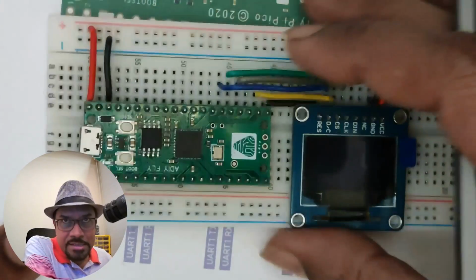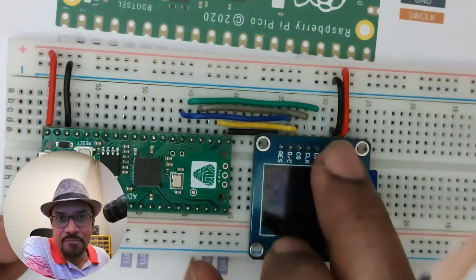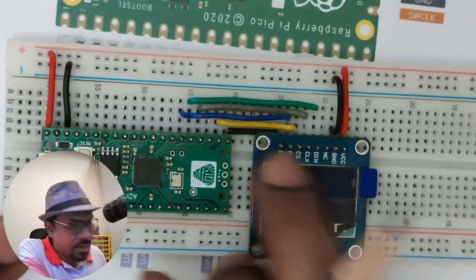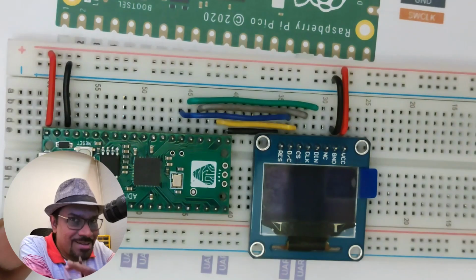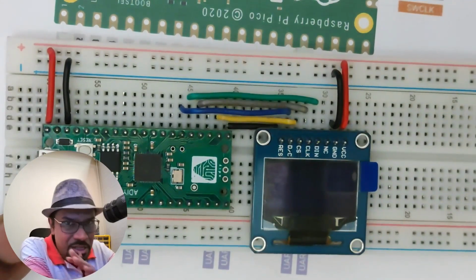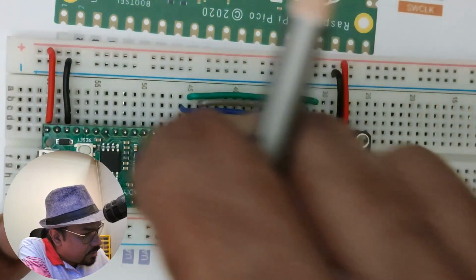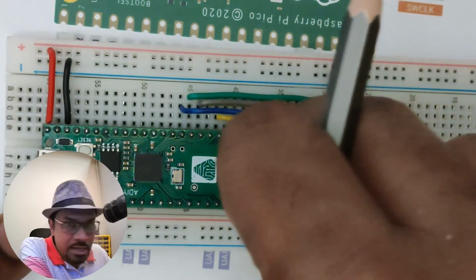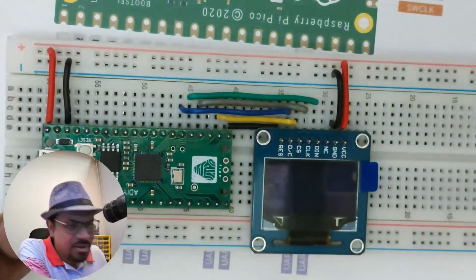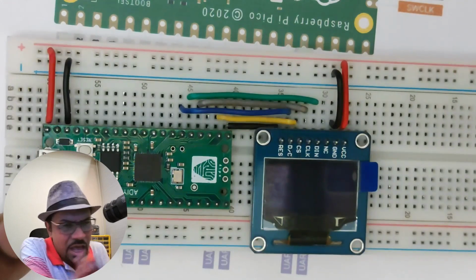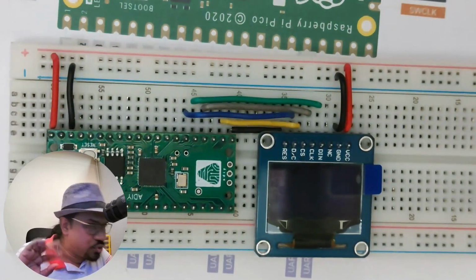Now, in order to test this, you need a library. This particular display, as I told you, the 8-pin Waveshare display, if it looks like this, would very likely be using an SH1106 with SPI interface, right? That's what you should use. So I'm going to tell you how to actually run the program, how to install the library on the Raspberry Pi Pico, use that library and test it across, right? It'll be a very simple program. It will just print a hello world kind of a message. So just hang in there. I want to just switch the screen.